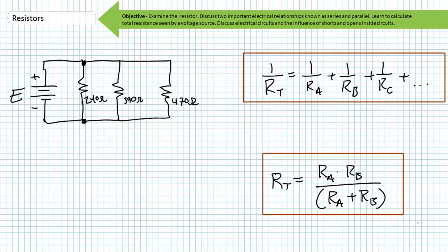How might one use a 2 resistor formula for a 3 resistor parallel relationship? The answer is cunningly. Use the same tool twice. I know it seems like I'm promising twice the work, but am I really? Each single repetition of the 2 resistor parallel formula is substantially lighter work than using our all-encompassing parallel resistance formula once. Additionally, each repetition, because it's lighter work, has a much greater chance of success than a single repetition of a messy and complicated formula. What do you want? A wrong answer after a lot of confusing work, or a correct answer after 2 easy moves? I know what I'd choose.